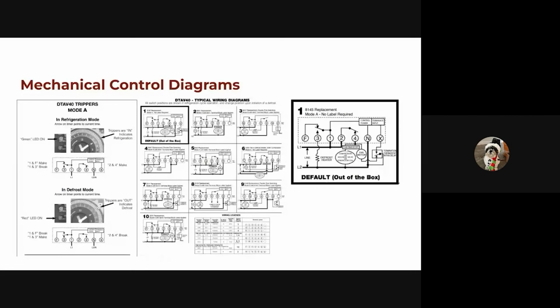Okay, so maybe this illustration is showing a thermostat controlling the compressor. So what does control that compressor, like in the case of a self-contained case? All our self-contains are electronic, but it could be just as simple as a temp sensor. Okay, so there's a temp sensor controlling this compressor, because you wouldn't want that just running 24/7. If your evap's already at temperature, then there's no reason to keep pushing more refrigerant through it, because you've got to maintain some kind of balance of your vapor versus liquid.